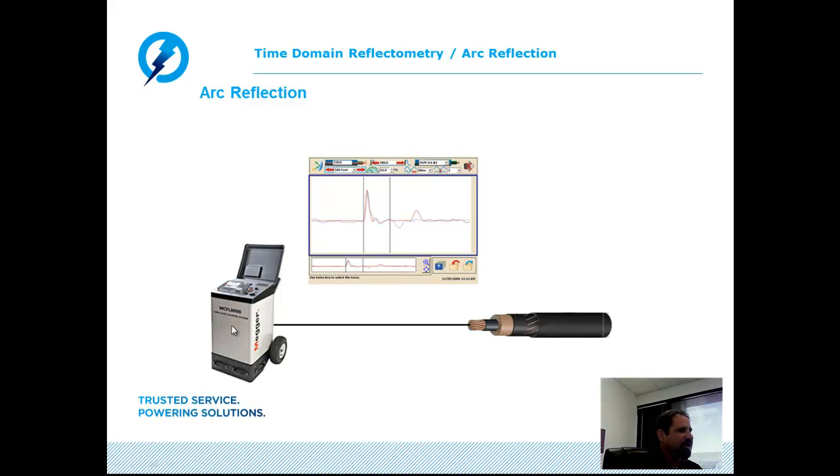We then discharged the high energy or high voltage of the thumper into the conductor of the cable under test. When this high voltage impulse caused an arc at the fault, at that moment of time the fault became a short circuit, and we were able to reflect a pulse echo pulse off of that short circuit, and on the high voltage waveform we see the negative reflection indicating the flash point or the point where the arc took place as a result of the high voltage thumper pulse.